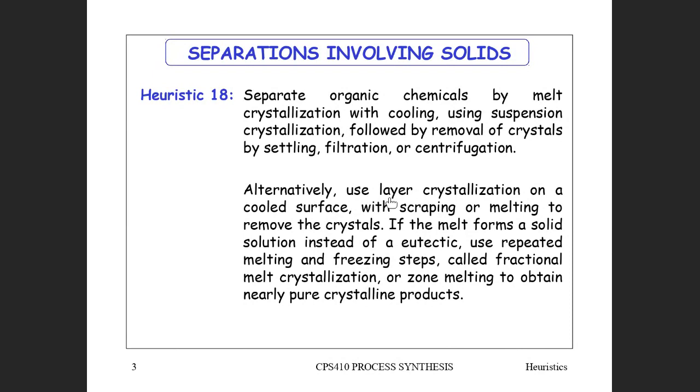Whenever you crystallize, you tend to find that you need an indirect heat transfer, or a cooled surface, and usually it sticks to that surface, and that's why they call it layer crystallization, and therefore you have to actually scrape. You've got to use mechanical scraping to take it off, or you can add heat in a cyclical sort of way. So in my opinion, this heuristic 18 is more suited when you've got specialty chemicals,